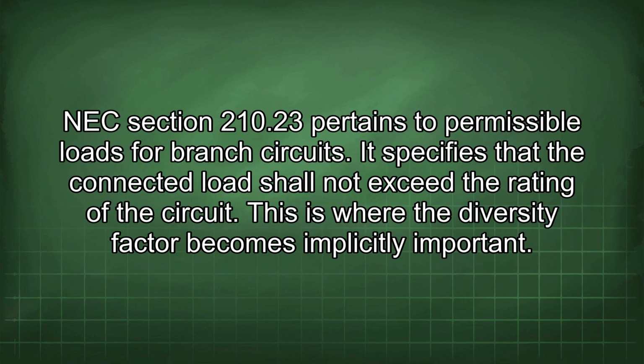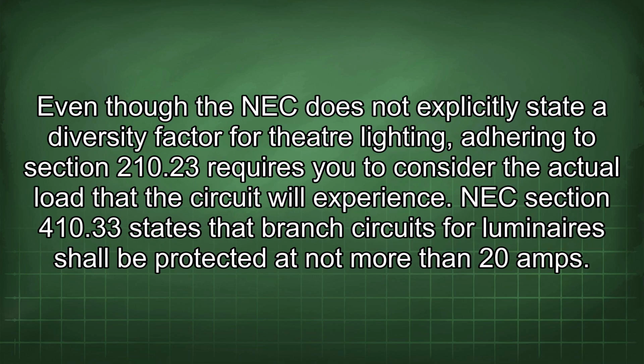NEC Section 210.23 pertains to permissible loads for branch circuits. It specifies that the connected load shall not exceed the rating of the circuit. This is where the diversity factor becomes implicitly important. Even though the NEC does not explicitly state a diversity factor for theatre lighting, adhering to Section 210.23 requires you to consider the actual load that the circuit will experience.